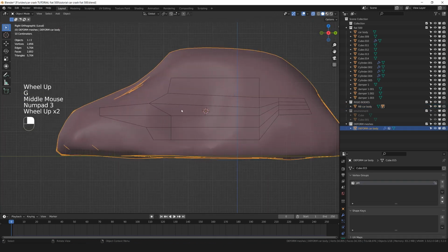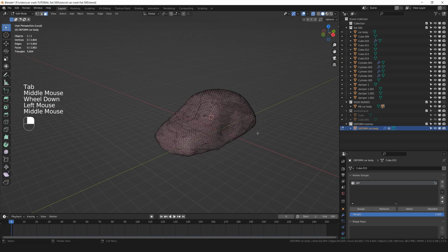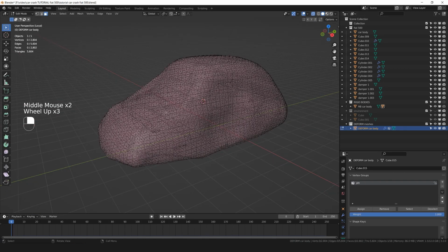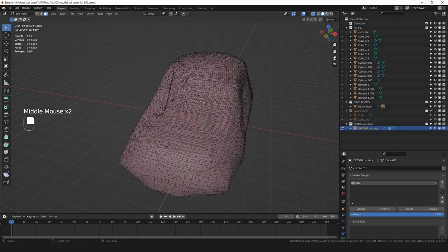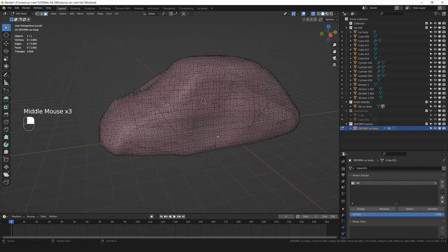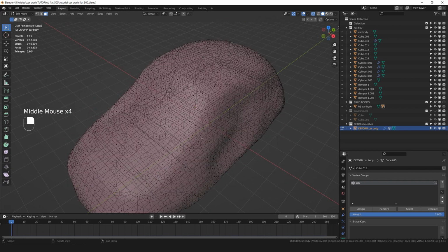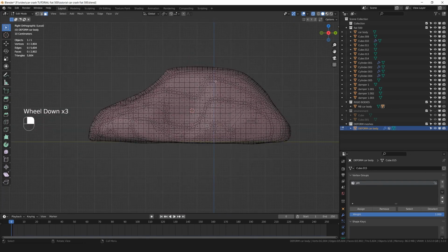The concept is to add a vertex group, which is basically you select some vertices of this and you assign them to this vertex group, and those vertices are not gonna deform in any way. They're gonna be stiff. But the problem is, we want to deform this car, so we can't touch these vertices, right? And so my big idea was to create a vertex group inside the mesh. So now I'm gonna basically add more vertices inside the cloth, separated from these vertices, but still part of the mesh of the deformation.